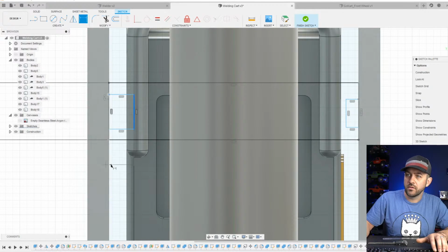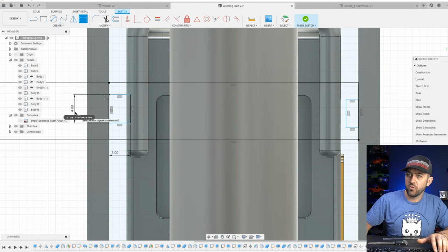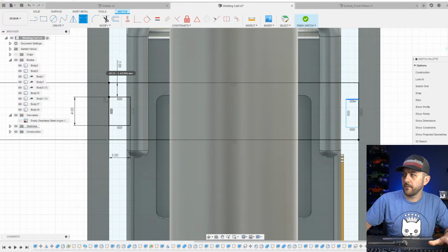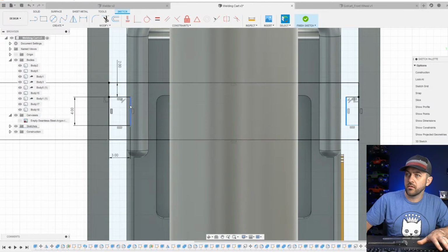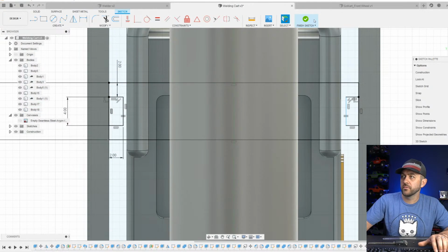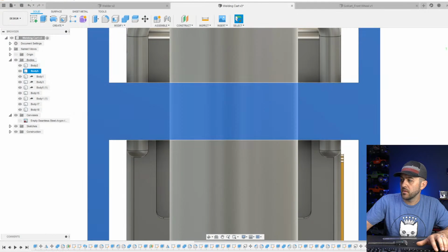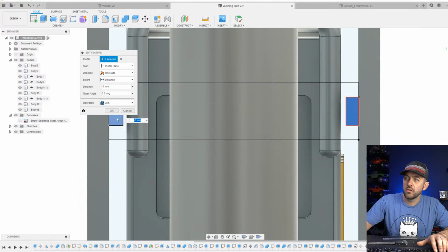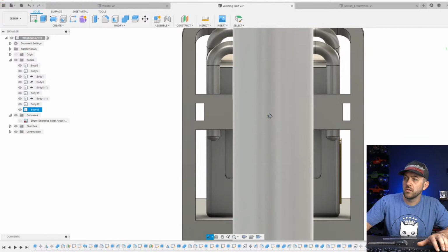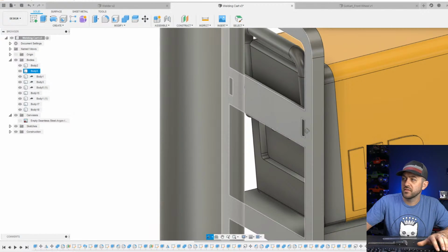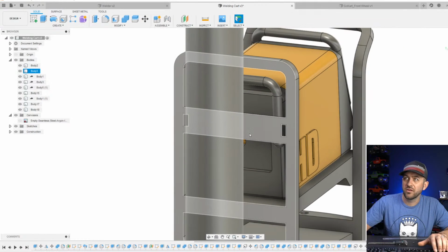Let's go. 3 millimeters wide, 4 tall, and that should give us 2 that we can use here. Make that. I think 3 millimeters is too wide. We'll go 2. There we go. So you can put your chain through those slots now. If you need them a little larger, you can always file them.